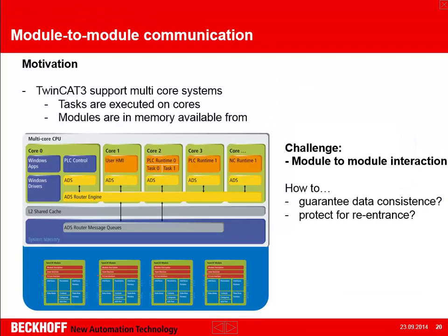One of the interesting questions is, hey, if TwinCAT 3 is executing up to 250 cores, this is what our system is designed for, and if I can create as many tasks which are just limited by memory, then the task is executed on specific cores, and the tasks are triggering modules, and the modules are somewhere in the kernel memory, and then the modules being executed from different tasks should somehow interact with each other, even if they are running in different cycle times.